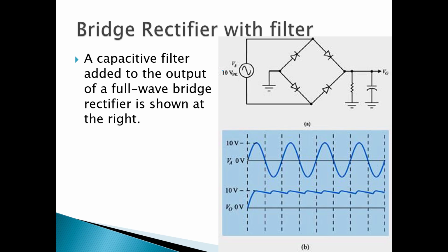So here's that same circuit I just did. The same circuit right here. We just analyzed this. And here we are with our complete voltage. And here's the capacitor. The capacitor kicks on here, and here, and here, and here, and everywhere, right? So this is smoothing faster than the half wave because it has all the little peaks in there. So we call that a filter, and it often runs real well.